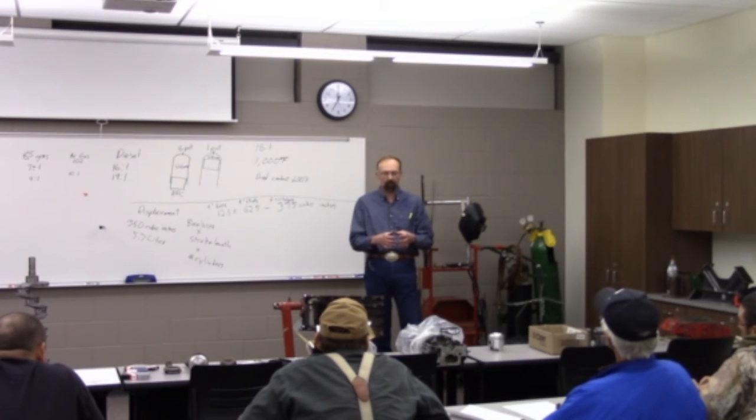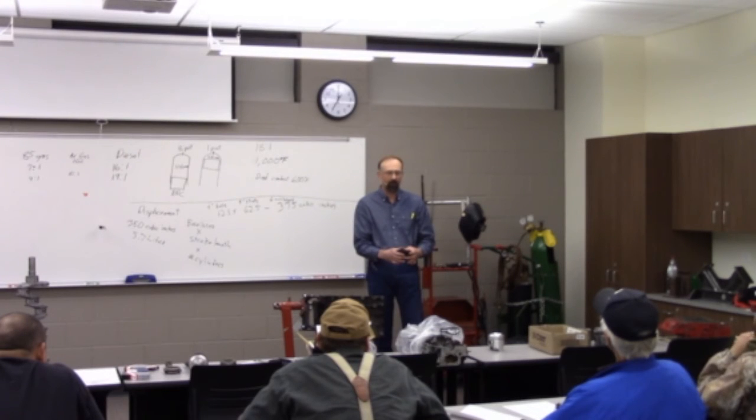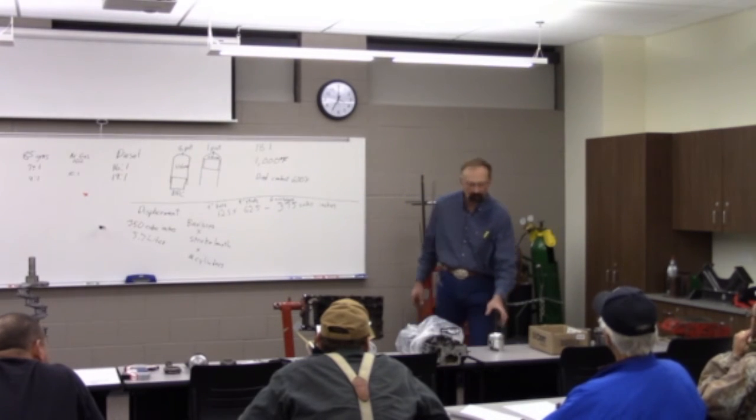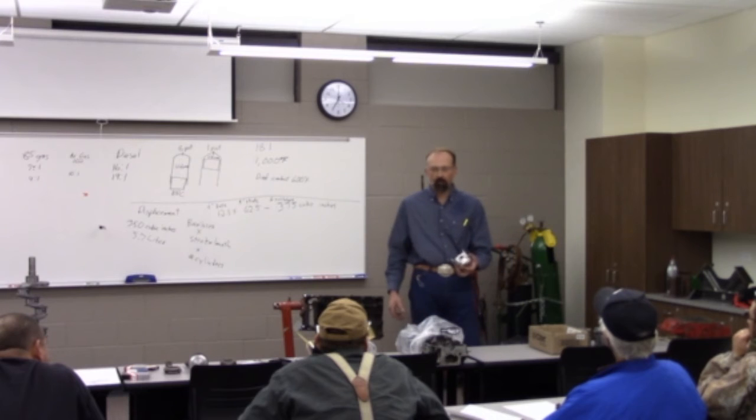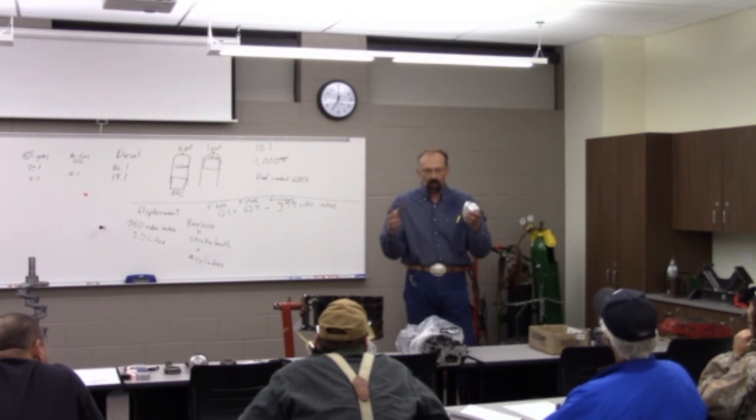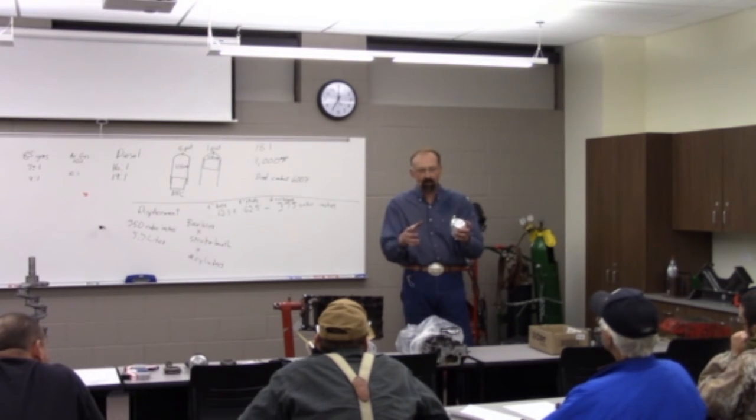And what Rich was talking about to start with is there are a lot of engine designs where that cylinder is manufactured as a sleeve that's pressed in it to begin with. And in many cases, it's not a tight press fit. It's something you can almost push in with your hands. And then a little bit of a puller will suck a worn one out. And in those designs, typically when you buy a new piston, you're buying it with a sleeve. So you're buying a piston and sleeve set because you're going to replace them both together.